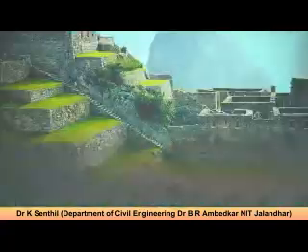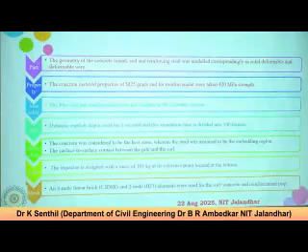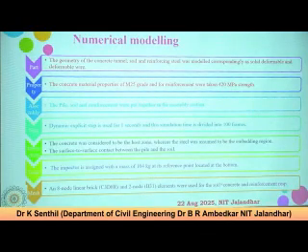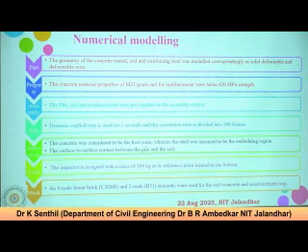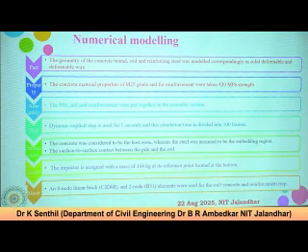Okay, so if you look at the part module, you have to model the elements part-wise. Then there is the property module, so you model the properties, then the section you have to define, then assign it, and then come to the assembly. You can assemble both the reinforcement as well as steel, concrete, whatever it may be.